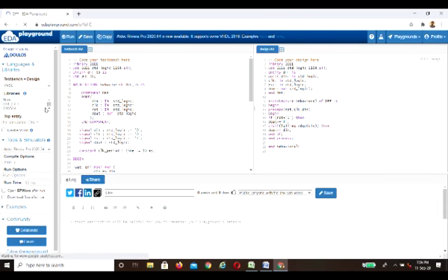After that you have to mention the top entity name. In your test bench the top entity name is DFF_TB. So copy this name and paste it into the top entity section. Now you have to select the Open EPWave option, because after the run, if you want to check your output waveform, you need to click on this option, Open EPWave. After the run, a browser tab will automatically open, and in this browser you can easily check your waveform.